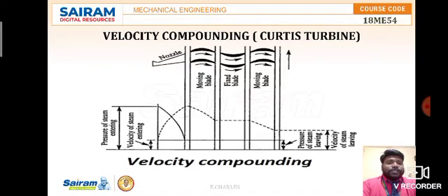That steam goes inside the nozzle and comes out of the nozzle. Since the exit area of the nozzle is different from the inlet, there is a convergent portion in this nozzle, so steam comes out with a certain velocity, and a pressure drop takes place.